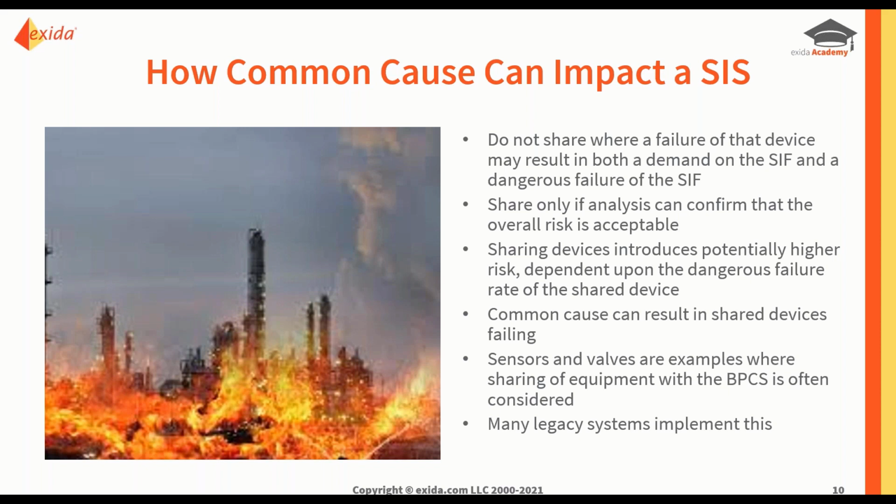And those of you that have been on my class know when I talk about the requirements for an IPL to qualify. So it has to be specifically designed to be able to prevent the hazard from creating the consequence. It must be completely independent of all other protection layers. It must be dependable in terms of having sufficient ability to provide random failure protection as well as systematic failure protection. And it must be auditable, which means it's got to be testable, and also maintainable.